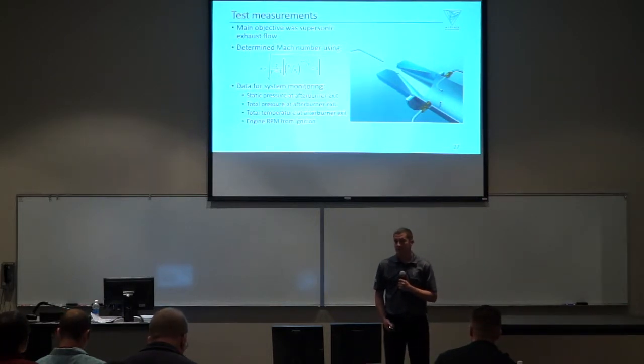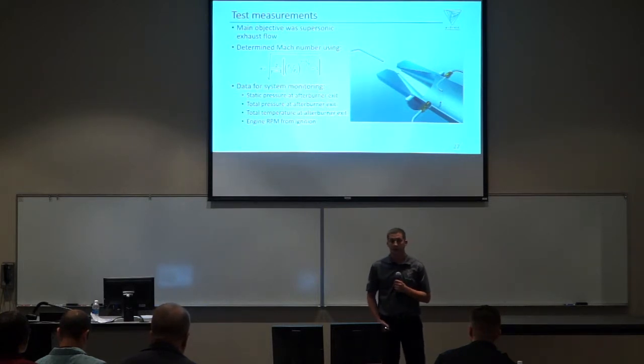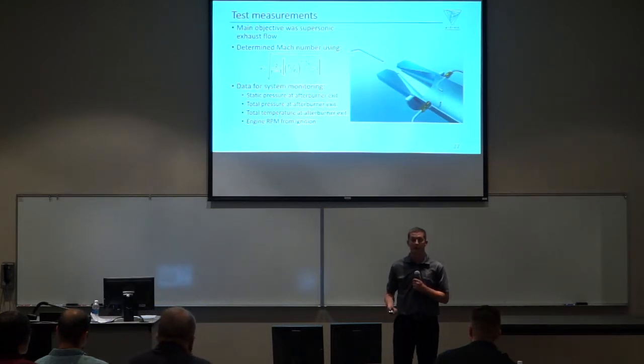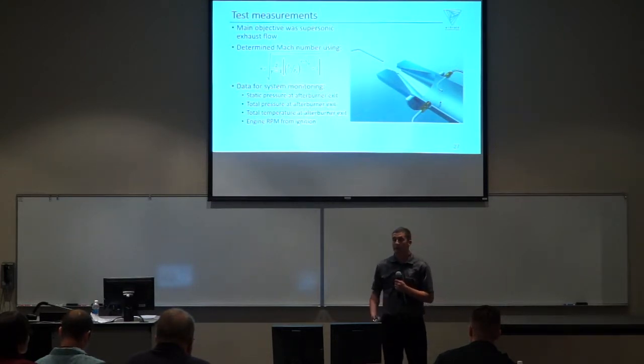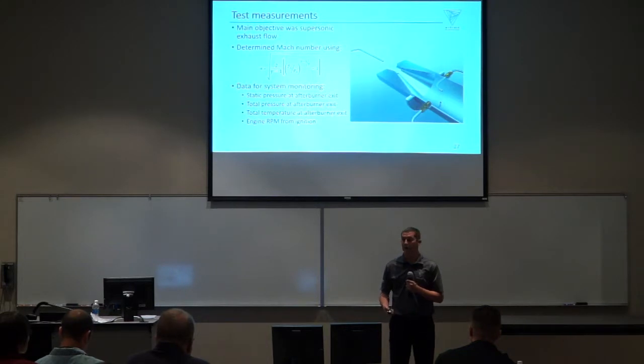Other measurements that were taken were more for a better understanding of system behavior and for troubleshooting. Some of these measurements included the static pressure and total temperature measured at the afterburner exit. And then we also recorded engine RPM from the ignition trigger signal of the engine.